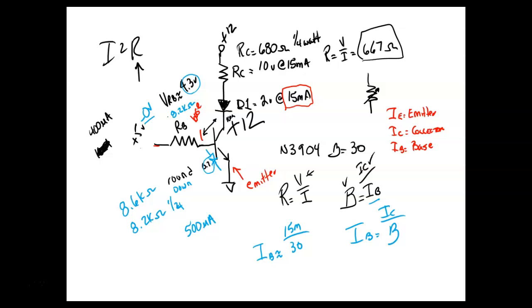So it stores the charge there. It gets a lot of majority carriers there. So when we turn this thing off, it doesn't turn off instantly. It's got to discharge that collector charge. So these guys right here, once you saturate them, it takes a minute amount of time to unsaturate them. So you can't switch them on and off. You can switch them off and on. Really, what to us seems like real fast, but inside computers, we're in a nanosecond world inside those computers.